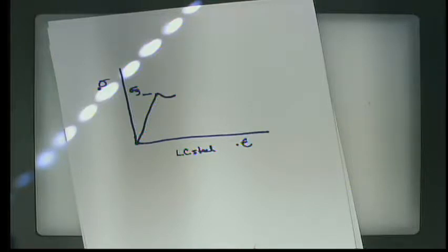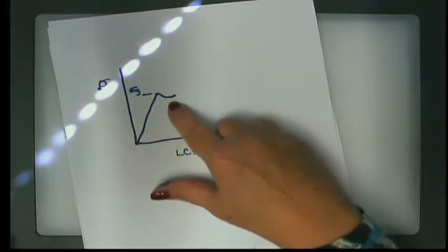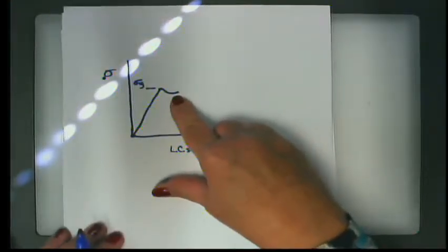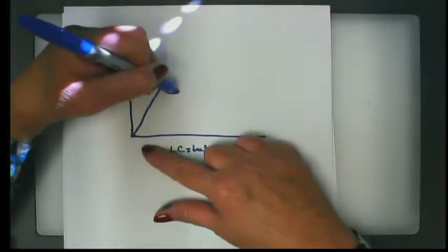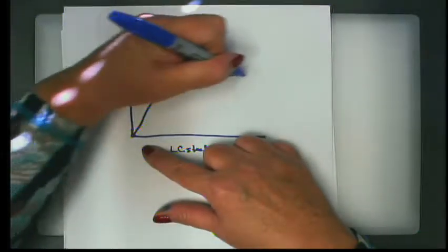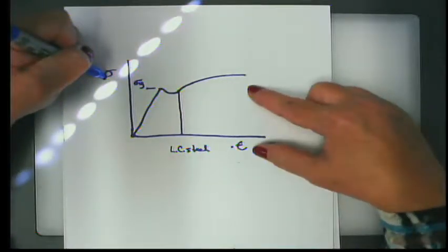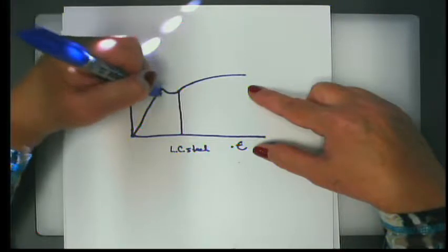Now, you can see that with other things like silly putty. If you have a little sausage of silly putty and you pull on it, it'll get thin, right? And then it will start to sort of float, you know? So you see that you can pull on it less hard and it will still continue to elongate. And actually the rate of elongation will increase. Then what will happen is it'll sort of change its mind, and it will require more stress to continue elongating.